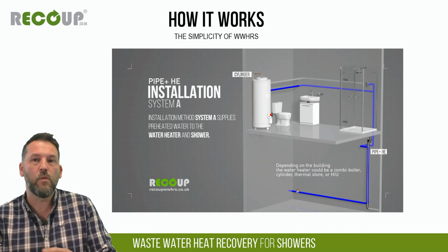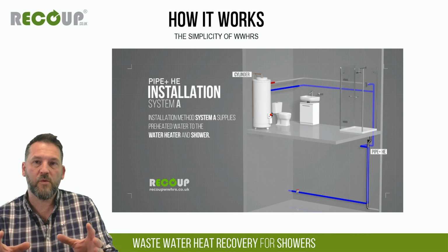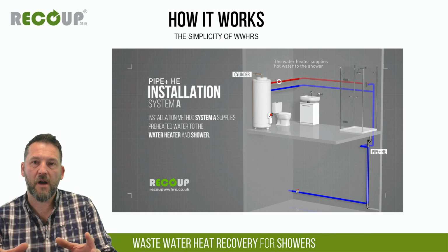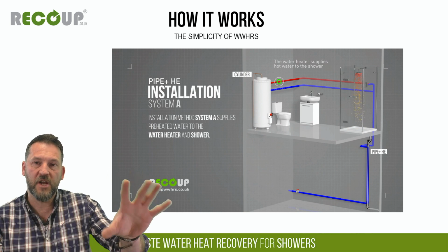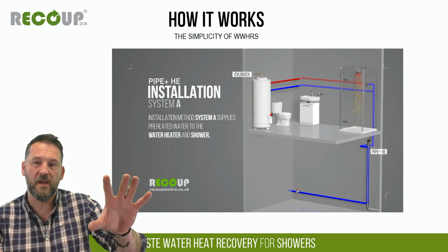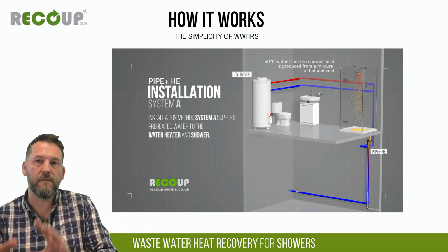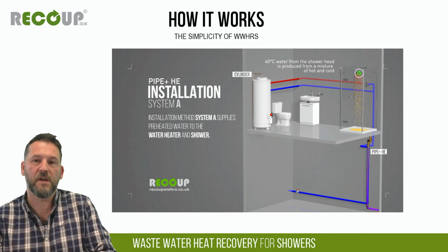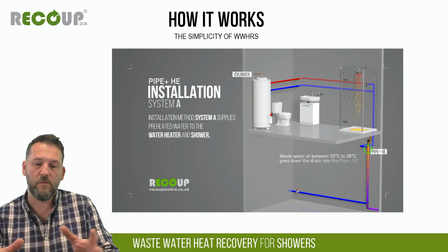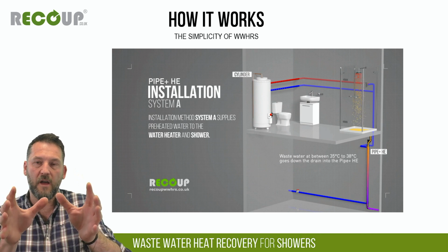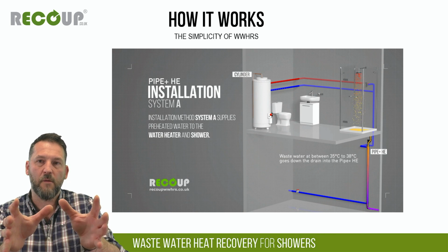So normally without wastewater heat recovery, when you're showering, that kind of comfortable 40 degrees or so coming out the shower head is a mix of around about 60% generated hot water, so 60% incoming hot water from about 55, 60 degrees, and about 40% incoming cold water around about 10 or 12 degrees in most cases. And then the mixer will adjust its ratio to give you that sort of 60-40 mix and a comfortable 40 degrees coming out the shower head.